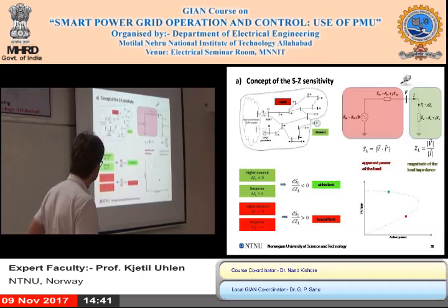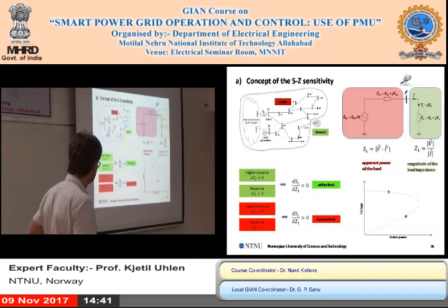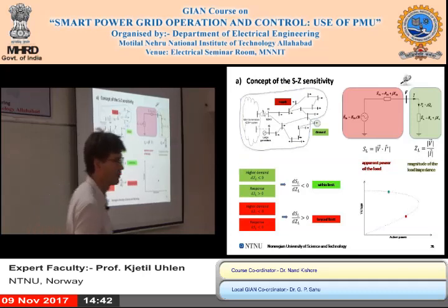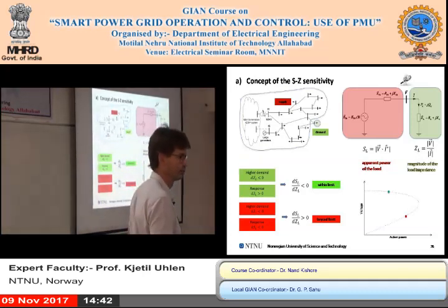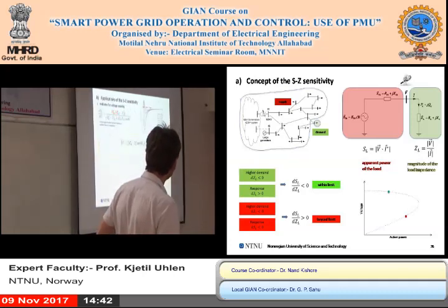And then you have a sensitivity that is basically negative. If it comes to 0 and becomes positive, then you most probably have passed the maximum loadability limit. So this sensitivity can be used as an indicator itself.